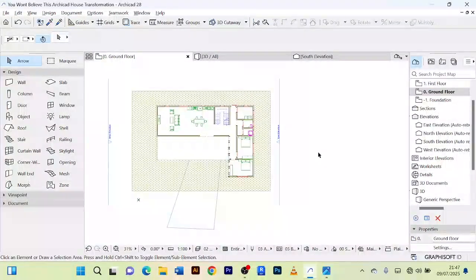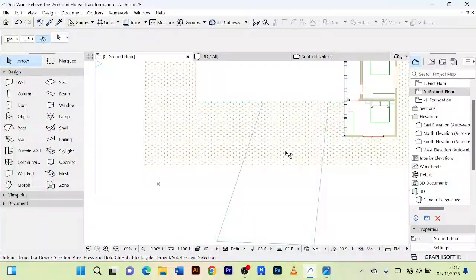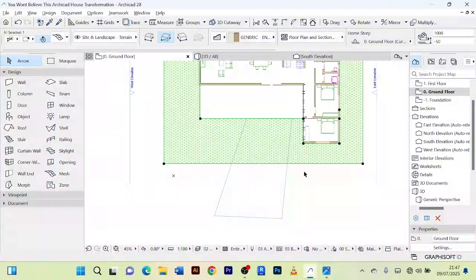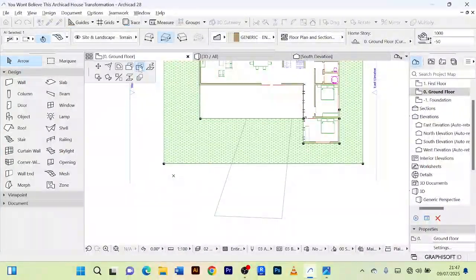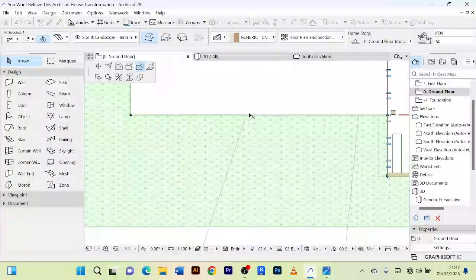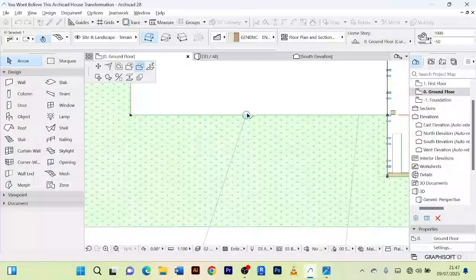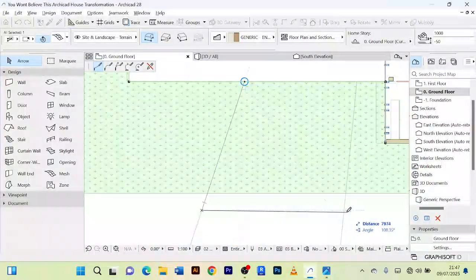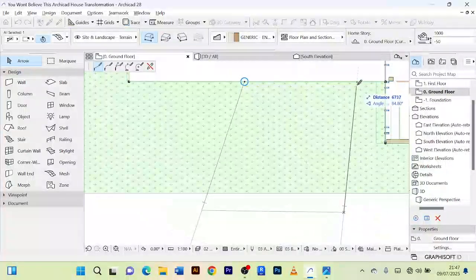So you can do a lot of things here. Even this part you can remove it out so that it doesn't interfere with your pavement. So you just click on this black dot, you click on that minus. This one here you can draw using this other method so that you don't get stressed. Otherwise, if you use the square method, it will just draw a square.